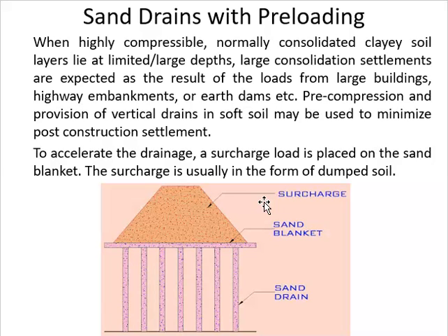If the subsoil is highly compressible with high values of settlements expected, and if the construction has to be started early, the consolidation process can be accelerated by providing preloading along with sand drains. This surcharge placed on the soil further accelerates the process of consolidation.